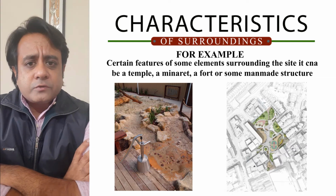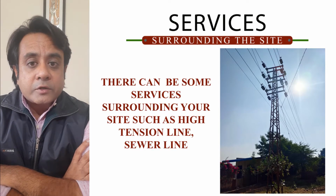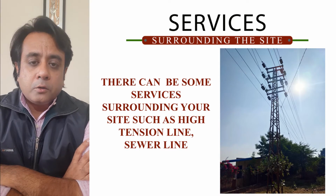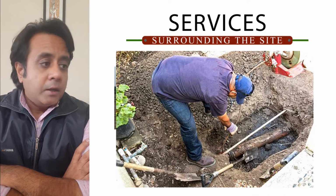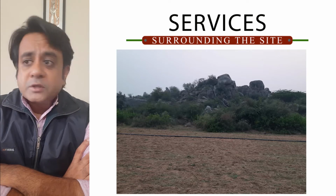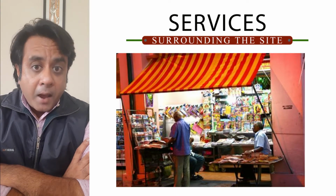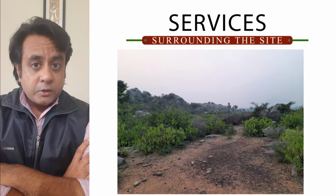Also, there are certain features which talk about various services, like sometimes you have a high tension line which is right across, or maybe right on the side of your property. There could be a sewer line running outside the property of the house. There could be a rockery. So it's important to know what your surrounding is, or there could be some commercial activity, there could be a shop, there could be anything which could impact your design process. So when you talk of site, you need to see the surrounding first.